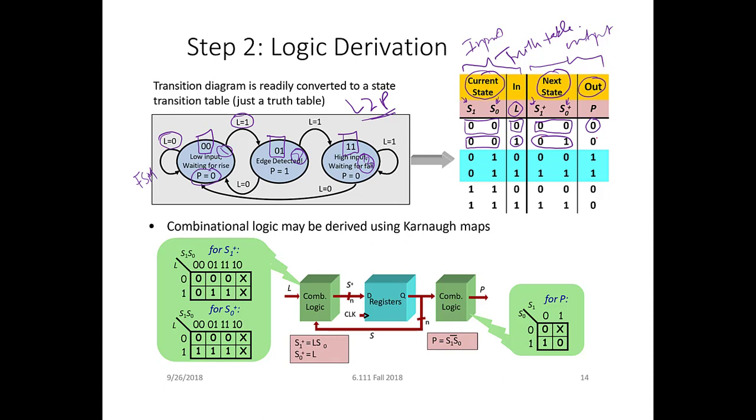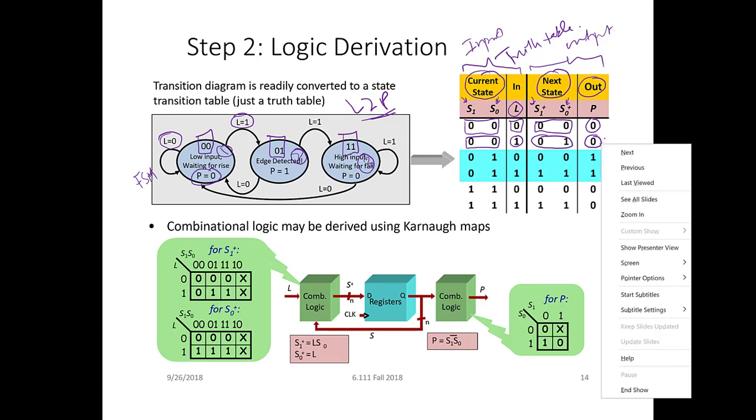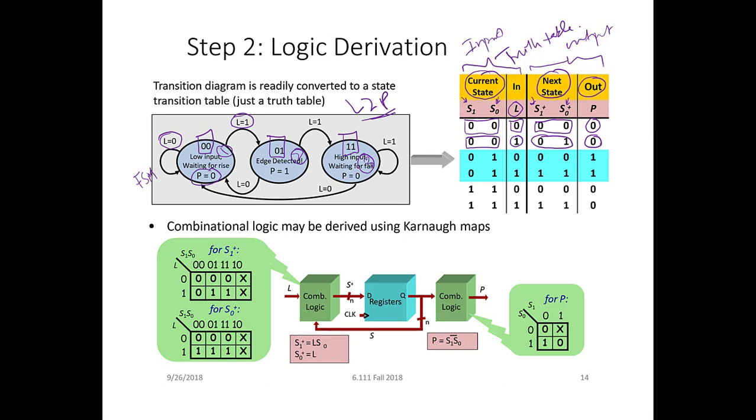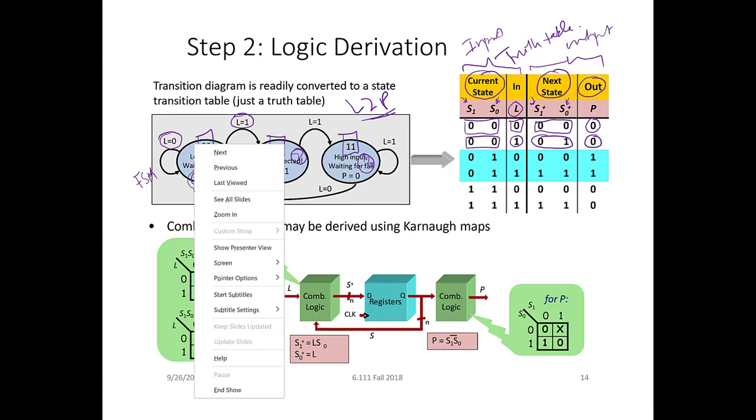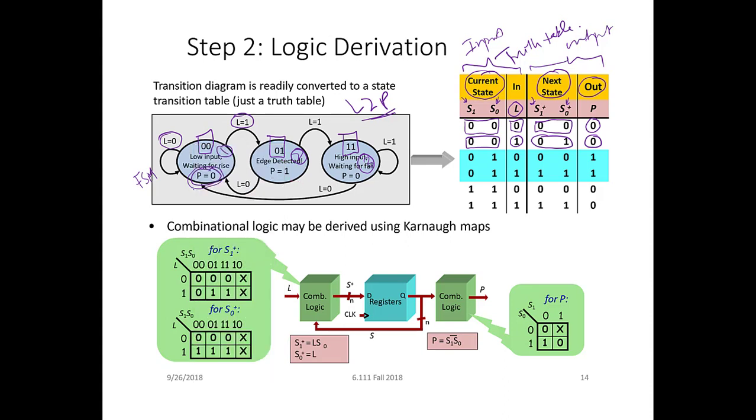Now it is important to note the output, because this is a Moore machine, the output is dependent on the present state. So we will write the output from bubble 1, and not from bubble 2. So this completes the first state and its 2 arcs.